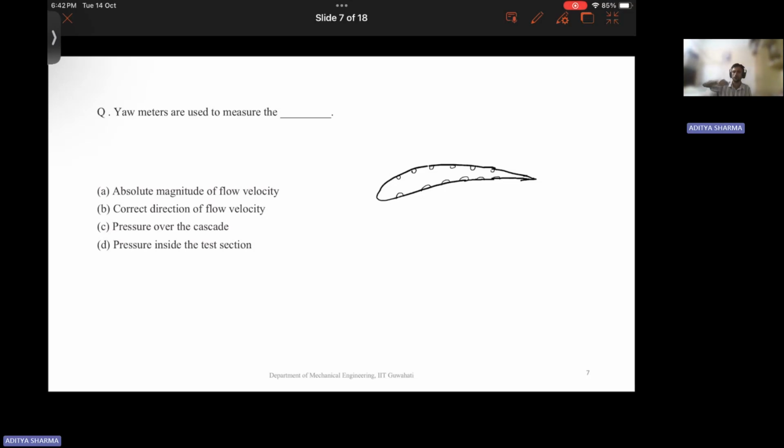Then you have tubes from here passing through. For all the ports, somewhere you'll have the exit of these tubes, wherever you are measuring the pressure, be it your manometer or some other pressure transducer. So this way you do it basically. These ports are on the surface. This was drawn in the lecture, so I'm just elaborating a bit more.